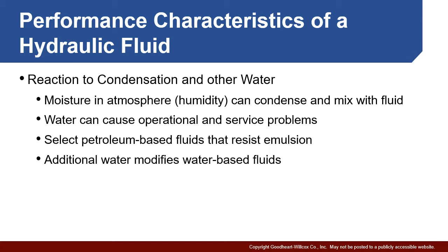And this allows us to actually separate out the water. And it's one of the functions we'll see of our reservoir, that when the oil and any type of water is in it, it's going to settle to the bottom of a reservoir. Keep in mind, we also have a number of water-based fluids that are used in hydraulics. You may think, well, then why would additional water be a problem? Well, the fact is that water is going to change the properties. It probably will have an effect on viscosity. It definitely may have an effect on wear. So when we even have water-based fluids, we want to keep the percentage of water consistent.